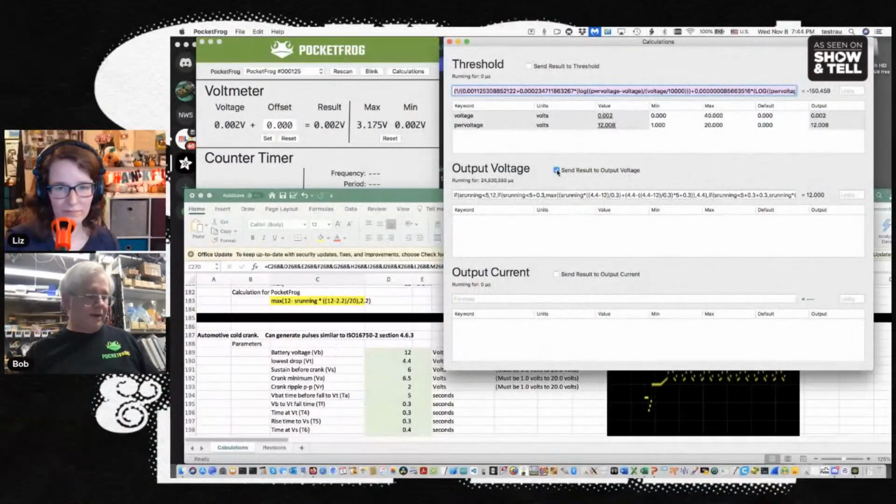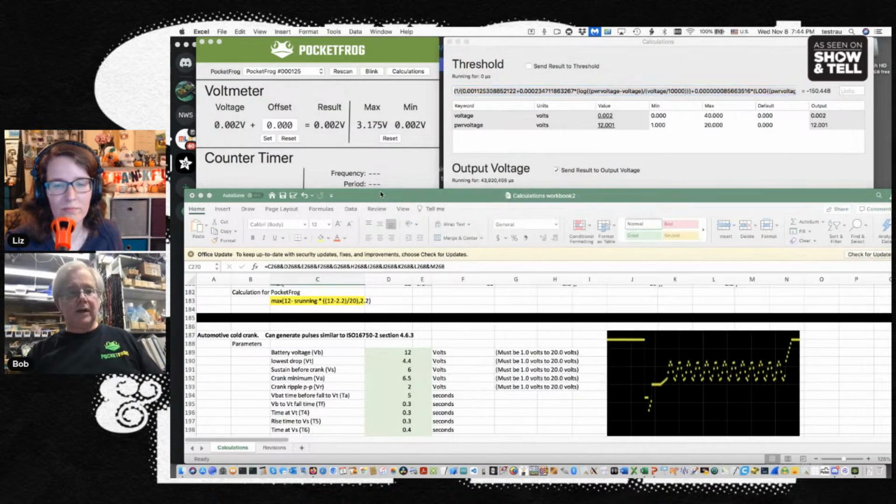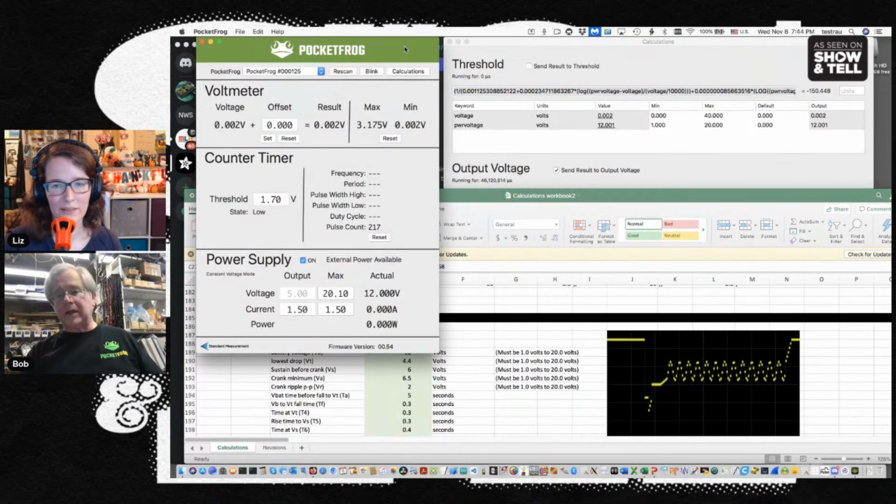So it's kind of an instrument in a class by itself. There isn't a lot of stuff out there. It gets around a lot of the hump of programming to generate repeated test waveforms, repeat a battery discharge over and over all night to make sure that your embedded software behaves correctly, saves the non-volatile parameters or whatever you need. It does a lot for design and test.